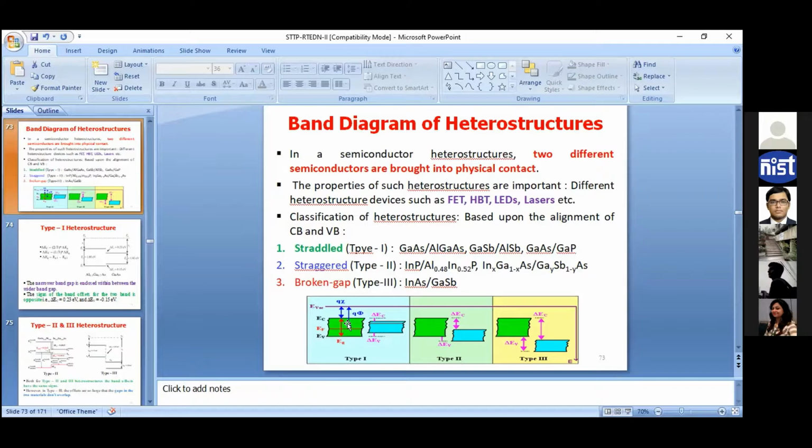But that can be done in a bulk graphene layer, and it is not a very clever way to retain the band gap. To get a particular defined band gap, since graphene is two-dimensional, let us cut it from two sides and make it a channel-kind of structure, a narrow strip.